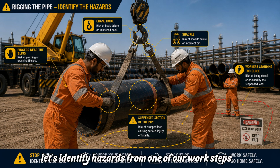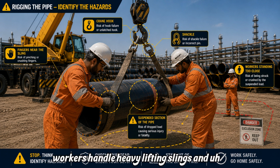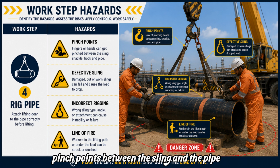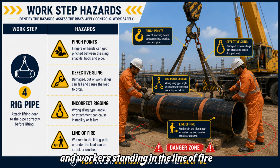Let's identify hazards from one of our work steps. During the step of lifting the pipe, workers handle heavy lifting slings and connect them to the pipe and the crane hook. Potential hazards include pinch points between the sling and the pipe, defective lifting accessories, incorrect rigging method, and workers standing in the line of fire if the load shifts unexpectedly.